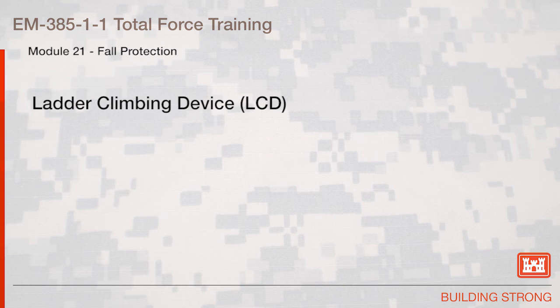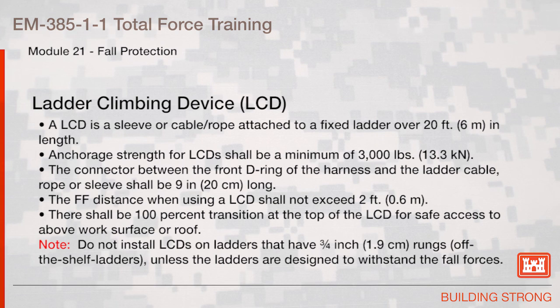Ladder climbing device. A ladder climbing device is a sleeve or cable rope attached to a fixed ladder over 20 feet in length. Anchorage strength for ladder climbing devices shall be a minimum of 3,000 pounds. The connector between the front D-ring of the harness and the ladder cable, rope, or sleeve shall be 9 inches long. The free fall distance when using a ladder climbing device shall not exceed 2 feet. There shall be a 100% transition at the top of the ladder climbing device for safe access above the work surface or the roof.